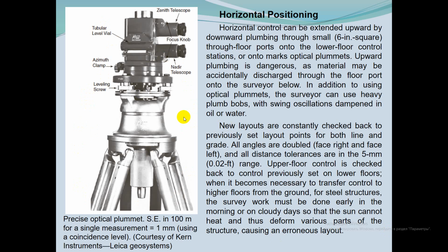This is a precise optical plumb, with a single measurement accurate to 1 millimeter in 100 meters, using a coincidence level. This is the azimuth clamp, leveling screw, nadir telescope, focus knob, zenith telescope, and tubular level.